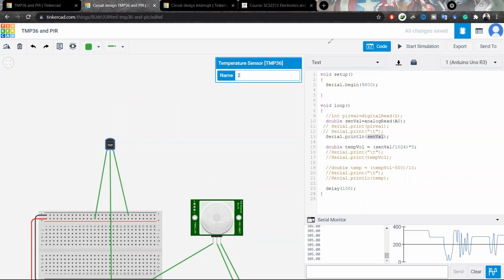So if that happens, in the graph, will that always be saturated? Sorry? If the input voltage exceeds the capability of the sensor, in the graph, will that be saturated at that point of time? Yeah, that is true. But if we can't read that sensor value, then there are other methods. You can go for the AREF, where you are referring to an external voltage.